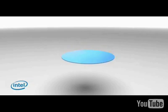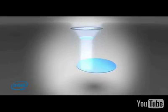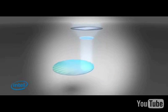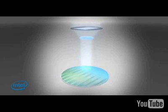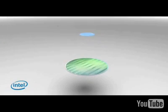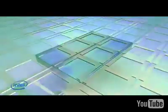And you spin coat what's called photoresist, which is a photosensitive material, on top of the wafer. And then you put it in what's called a scanner, which makes these patterns, which is what you will see on this. I'll pass this around in a second. Once you make the patterns, those patterns define, of course, these transistors. Whatever you put down kind of looks like this.